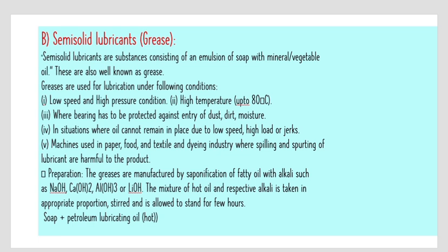It is prepared by saponification of fatty oil with alkali such as NaOH, Ca(OH)2, Al(OH)3 or LiOH. It is basically soap plus hot petroleum lubricating oil.